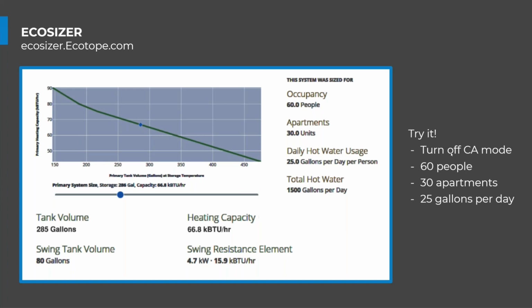And so during normal days, most people only use 17 to 18 gallons of hot water. Where we have more family occupancies, they typically use more water. And so we might want to adjust that 25 gallons per day up a little bit in that case. If you turn on California specification mode, which I did not note, there's some really great guidance in there on the default rates that they assume in California, which may be a place for you to first start with.